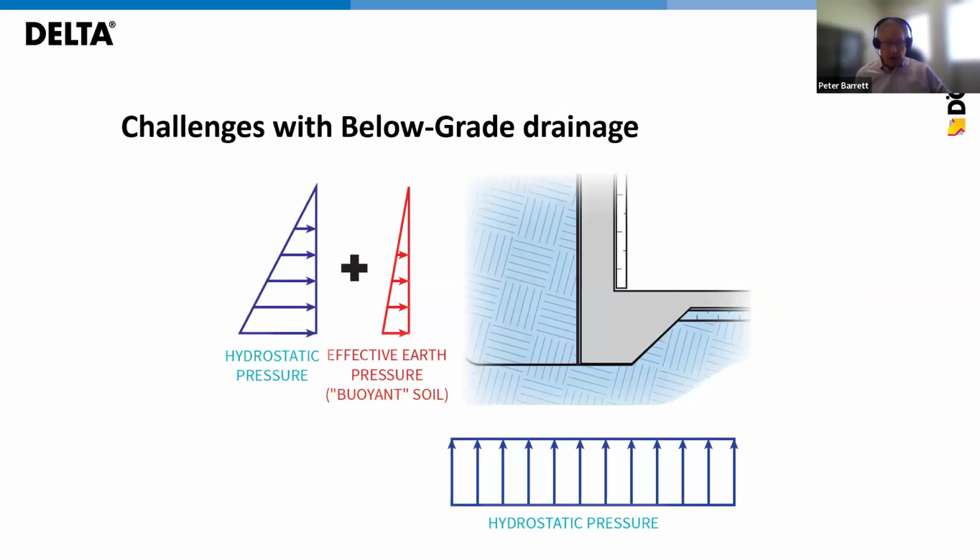The first step in building a new building is digging a hole in the ground. Sounds pretty straightforward, but in broad strokes, builders dig a foundation, pour concrete, and fill the hole back in. The problem, and it's a pretty universal one, occurs because the soil around the new foundation is less compacted than the untouched soil around it.